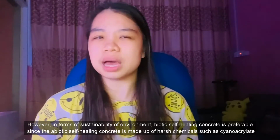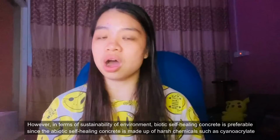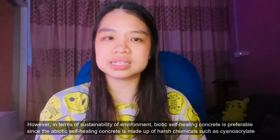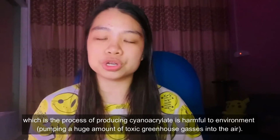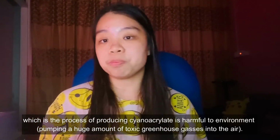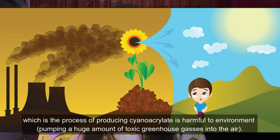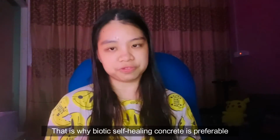Why? Since abiotic self-healing concrete is made up of harsh chemicals such as cyanoacrylate, and the process of producing cyanoacrylate is harmful to the environment, where they pump a huge amount of toxic greenhouse gases into the air. That's why biotic self-healing concrete is preferable.